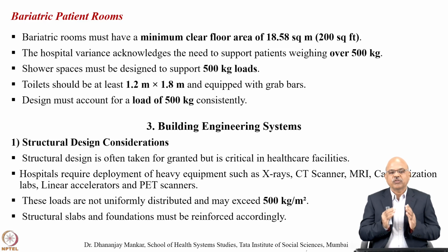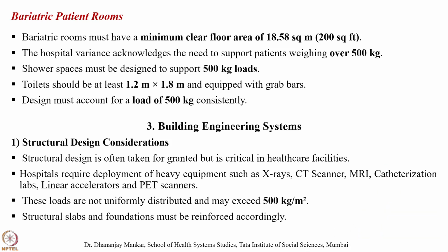Now, building engineering systems, and what are those? When you have a structural design consideration, you need to understand these are a given but critical in healthcare facilities. Hospitals require deployment of heavy equipment such as X-rays, CT scanners, MRI, catheterization labs, linear accelerators and PET scans. These loads are not uniformly distributed and may exceed 500 kg. Structural slabs and foundations must be reinforced accordingly.